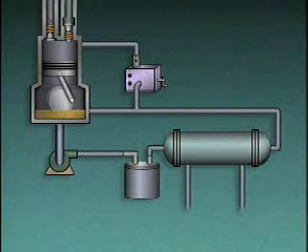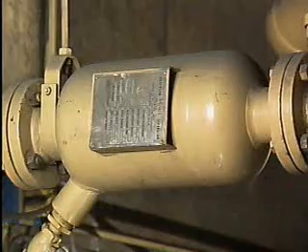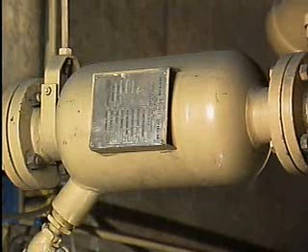Most reciprocating compressors that contain pistons use oil to lubricate the piston rings. During compression, some of the oil can become mixed in with the gas. This oil must be removed from the gas to prevent system equipment from being damaged. Oil removal is accomplished using oil separators.